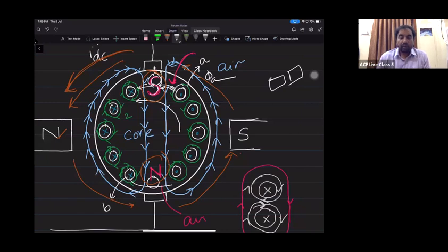Right. So, can I say for the production of the turning effect, how many magnetic fields are required? Two magnetic fields are required, and the relative speed between the two magnetic fields has to be 0. So, in case of a DC motor, who is trying to maintain the relative speed between the two magnetic fields at 0? A commutator. How? By changing the direction of currents in a particular conductor. If the relative speed is 0, then the poles are stationary. If the poles are stationary, then there exists a continuous attraction and repulsion. Because of that, there is a continuous rotation.